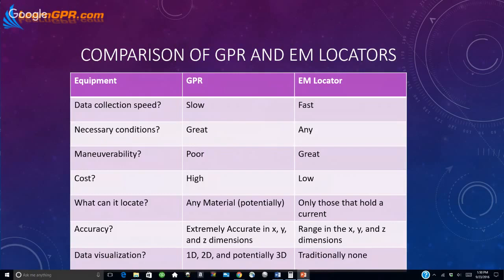Sometimes people tell me, I can't locate the pipe because it's too deep for my radar and the conditions are too poor. I say to them, can you see 2 feet within the surface, even if your pipe might be 8 feet below the ground surface? They say, sure, I can see 2 feet. Well, then can you see the excavation trench where the pipe was?